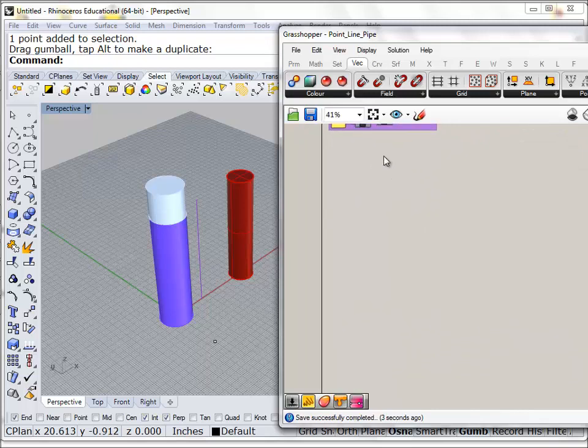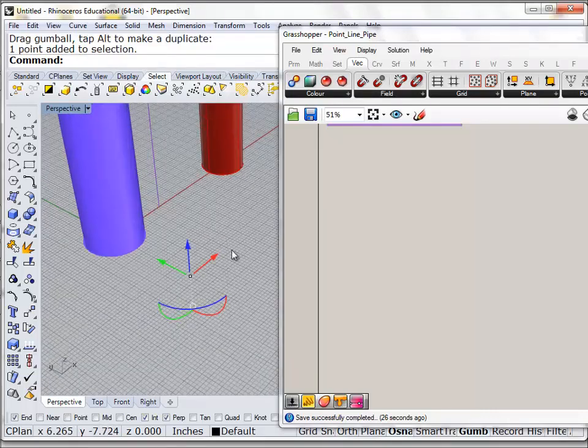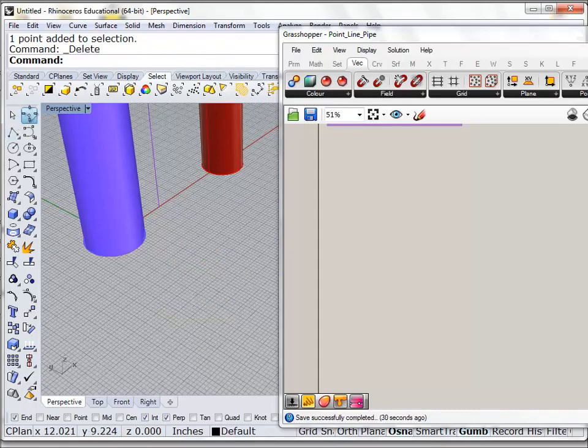Last thing we're going to look at today is how to reference geometry back into Grasshopper, because so far we've created geometry in Grasshopper and we are baking geometry out, but how do I bring information back into Grasshopper? So you're working with a project, the site boundary is very important, so we want to reference it back. So this is my baked point. I could reference this back, or I can construct a new point, it doesn't really matter.